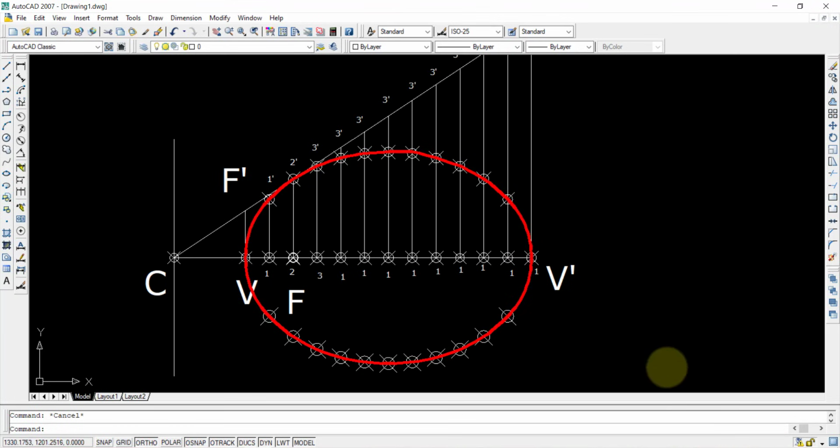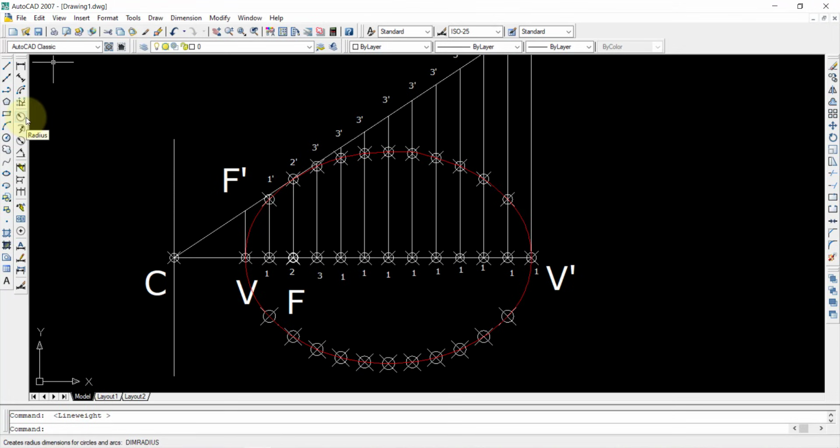Okay. So in some cases, they'll ask you to draw the tangent and normal to these curves. When they're asking to draw the tangent and normal, how can you do it? Select a point somewhere. In some cases they'll give you the point directly. In some cases they'll give you a point which is 20 mm from the focus or 50 mm from the focus. In that way they might give.